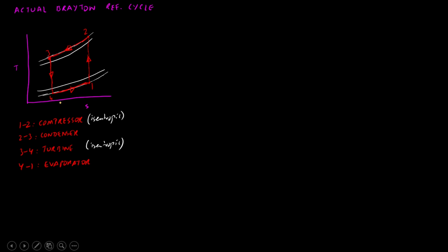So looking at, first of all, this compression process, what's actually going to be happening is that the entropy is going to increase, and entropy is increasing in this direction. So for it to be non-isentropic, this process would have to start at 1 and finish at 2. This is the constant pressure line. All of these are the constant pressure lines. So eventually I'm going to be here at 2 dash. So from 2 dash now,